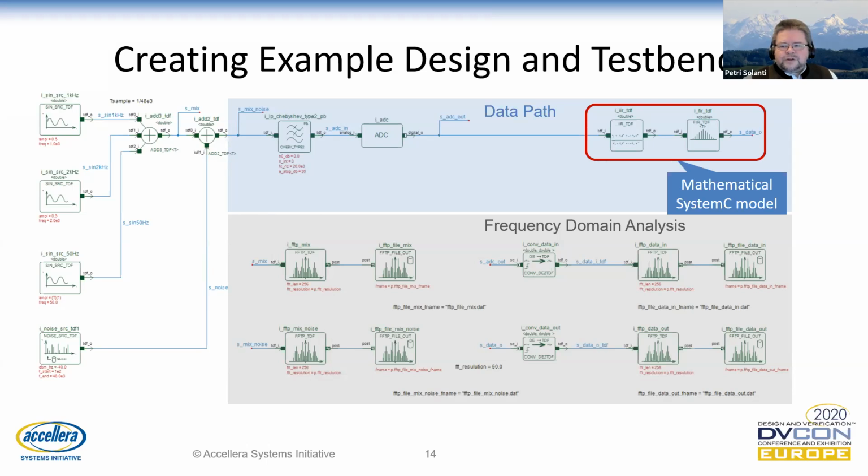The test bench generates an input signal with parameterizable signal levels. This allows testing the absolute limits of the algorithm to ensure that the design can fulfill the requirements. Algorithm performance is analyzed with frequency domain analysis using library components. Post-processing of the results can be scripted for automatic regression.